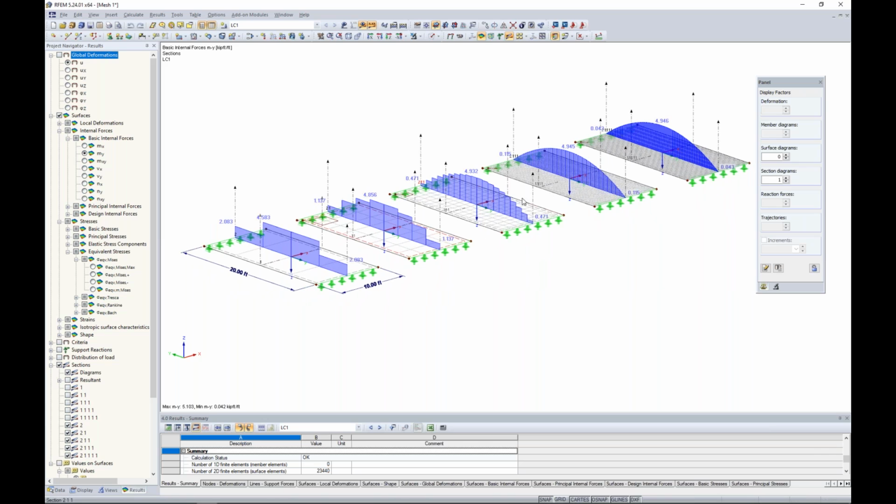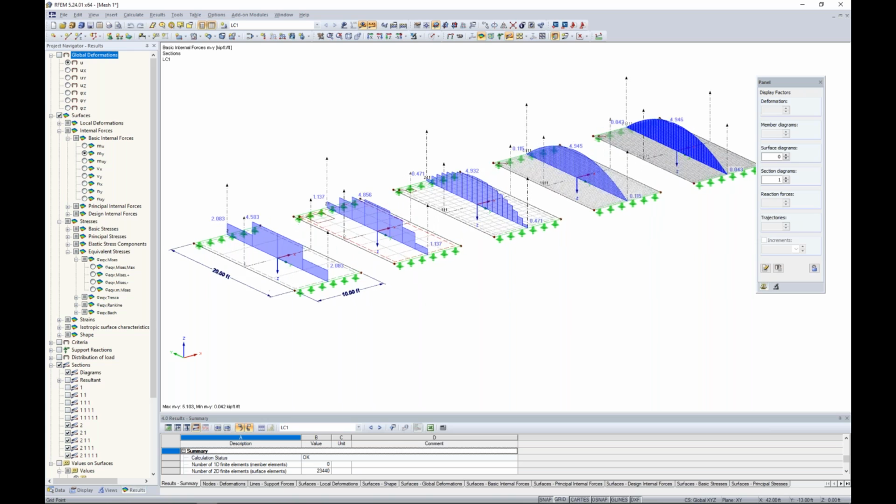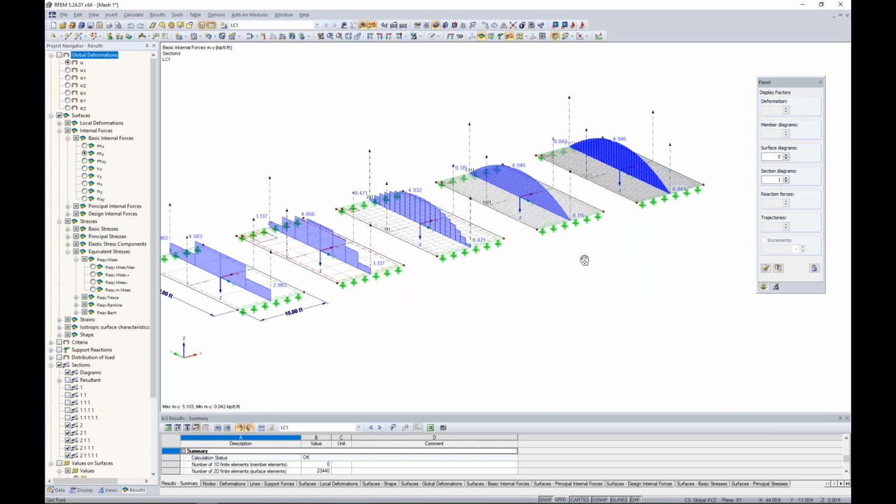And we're definitely getting a much more realistic view when we move into these more coarse meshes. The other thing to pay attention to are the values. So the max value here moves from 4.583, 4.5856, 4.932, but then we're getting into 4.945, 4.946. So at some point, our cost to benefit ratio, I guess, so to speak, where we're continually refining this FE mesh is really not drastically influencing our results.